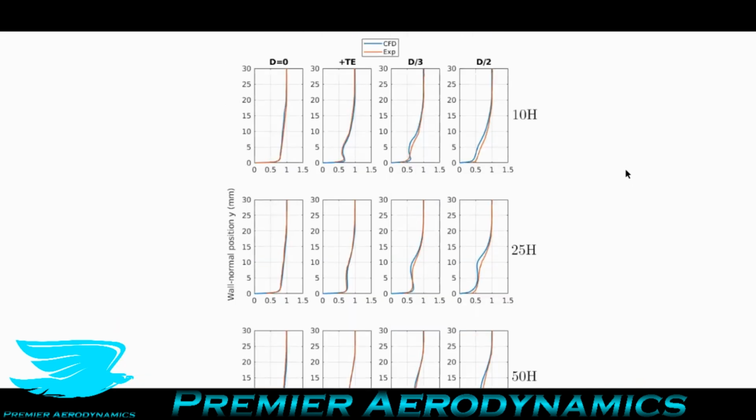So when you think about a vortex generator, you don't really think about how the momentum is being pushed into the boundary layer near the surface in terms of span-wise direction. So you might just think, okay, directly behind the vortex generator is doing that. But when you go a little bit further to the side, now the boundary layer is sort of untouched. So one thing that's good with this paper is that they look at the distance to the side of the vortex generator to see how that gets affected.